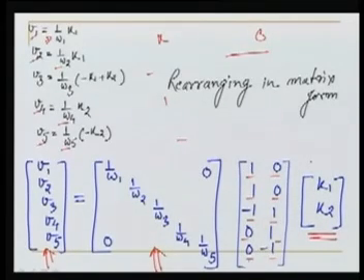We will make an important observation here. Now what is that observation? This is V, capital V, the residual matrix, and 1 by W1, 1 by W2, 1 by W3, 1 by W4, 1 by W5. This is the inverse of the weight matrix. The inverse of the weight matrix, we represent it by theta, which is called the cofactor matrix. And this is the K matrix, we say.